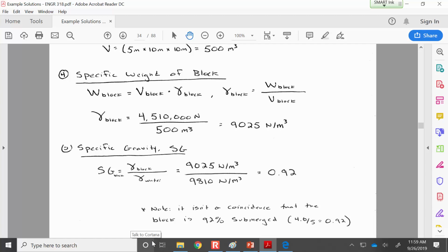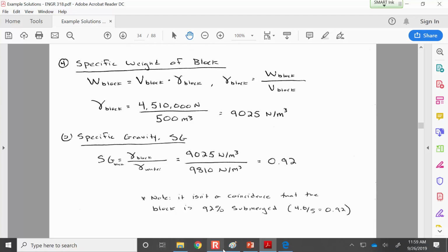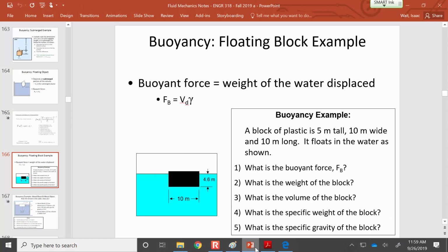Now, surveying the volume of an iceberg beneath the waterline is probably going to be tricky. So maybe the easier thing that we could say is that we know the density of ice. That's something you can look up out of a properties table. So if you know the volume that is up out of the water, then looking at the ratio between the density of ice and the density of water will tell you how much of it is below the waterline. I think it's something like 1/7 will be above the waterline, 6/7 will be below the waterline. All right, great question. Are there any other questions about this example?